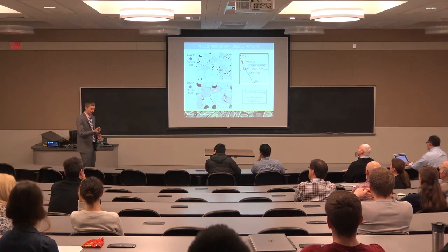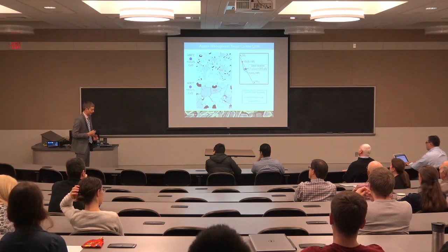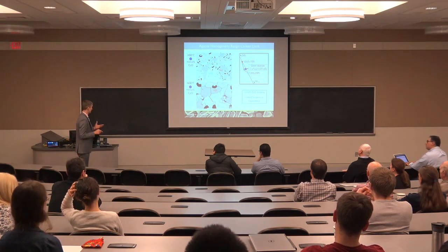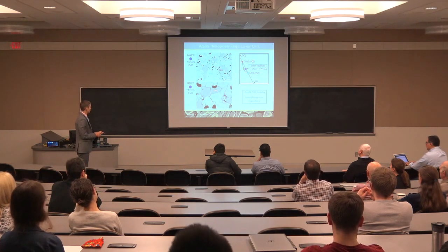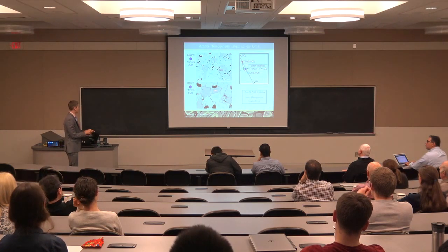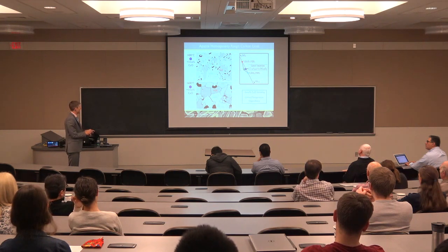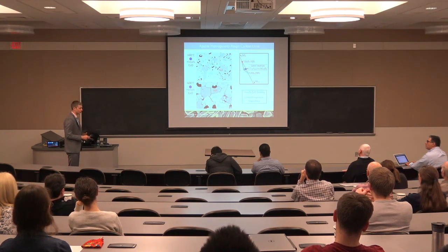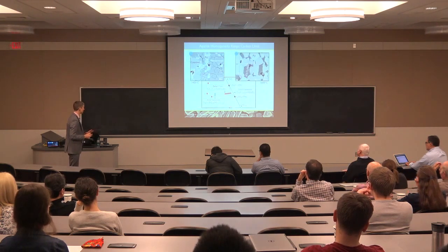Now, if we intentionally introduce that impurity, that alkali earth impurity, in this case it's calcium because that's the system we're interested in, just put 1% in, now apatite starts to show up in the microstructures. And so we can go in and measure the composition of that apatite and identify this as a three-phase triangle that captures the terminal composition of the apatite phase in this direction.